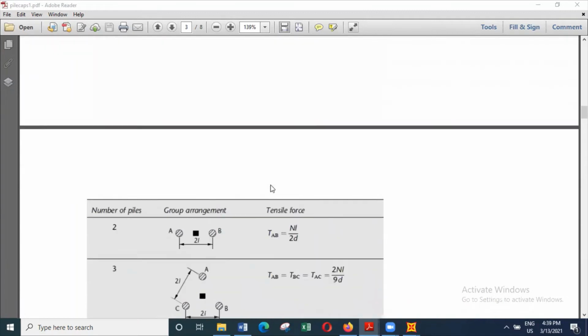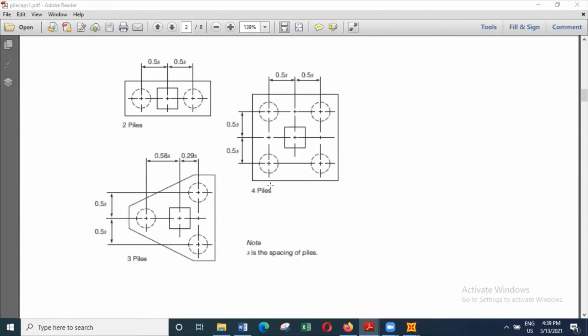But in a pile cap, if the distance between two piles is 3 times diameters and you have a column also supported, there isn't much space for punching shear failure, because when you are very close to concentrated loads, you get an enhancement of the shear capacity.